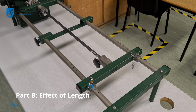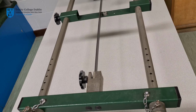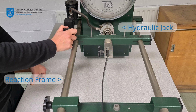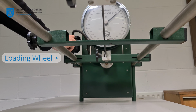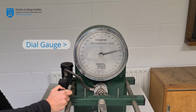For the second part of this lab, we will use the large rig to observe Euler buckling and demonstrate the effects of length and slenderness on how a strut buckles. The large buckling rig comprises a reaction frame and hydraulic jack which can be used to apply a force to the strut. Force is applied by way of a hand-operated wheel. The applied force can be measured in newtons via the dial gauge.